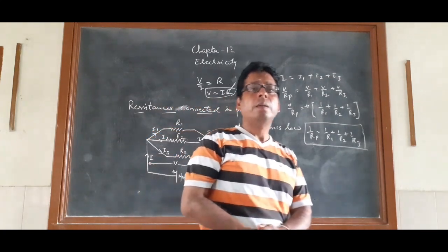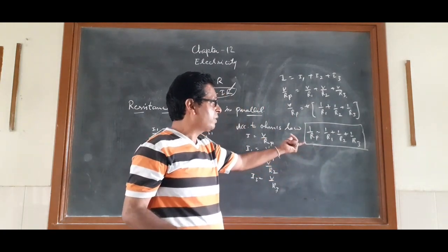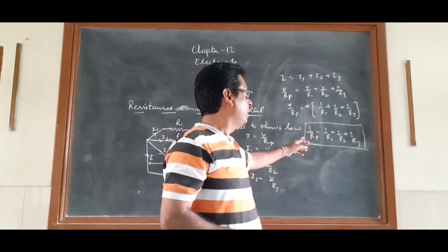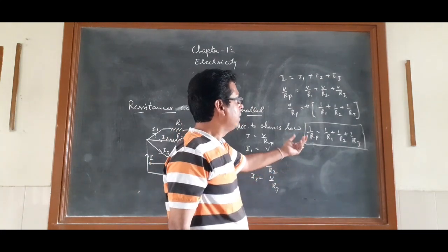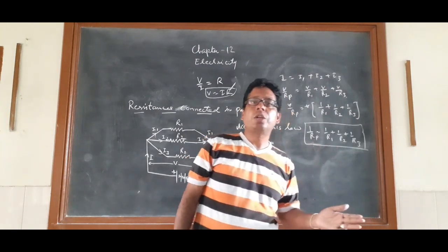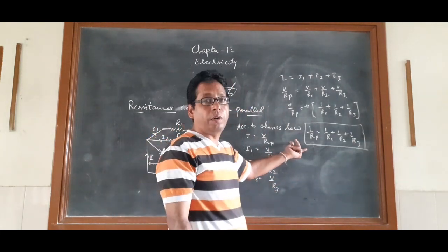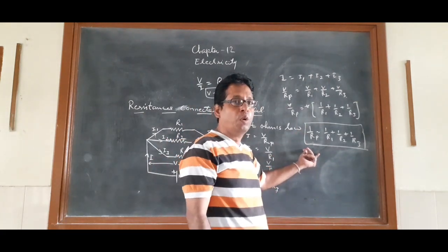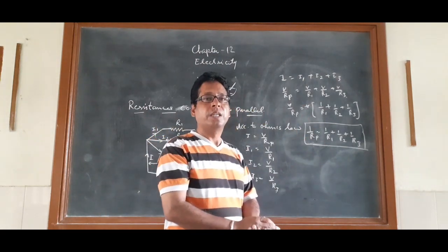Now the question arises, which combination is to be suggested for the wiring, series combination or parallel combination. We say that it is to be connected in parallel, because if one switch or one device is out of work, then the rest of the devices will work as usual, and moreover the potential difference at every point will be the same.